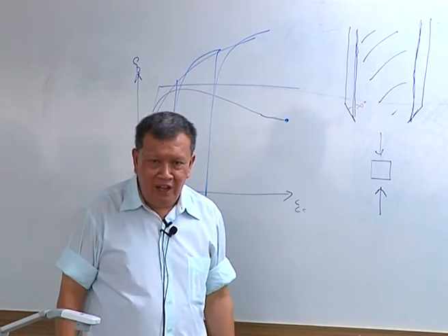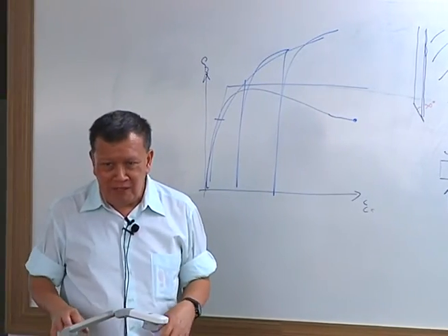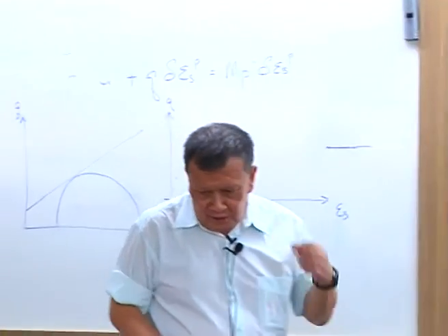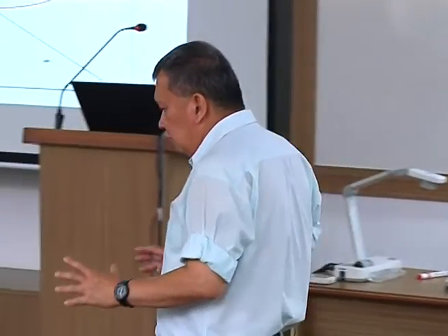You can't see anything. There's no more structure left in the soil whatsoever. It's like remolded, you know. So this is the thing with sampling. And so I think that you need to be careful. You need to be aware of the fact that sampling does disturb the soil.